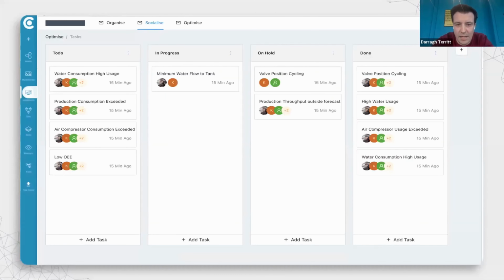And look, just to follow on from what Alan just said, a good simple example of this from a site that we were recently on. We worked with the site team. We collated all the data from a process SCADA system and a refrigeration system that were siloed apart historically. But within 3 hours of analyzing this data, the refrigeration SME was able to flag certain inefficiencies around an 85-degree CIP system being used to clean out the primary side of a heat exchanger when it got fouled.